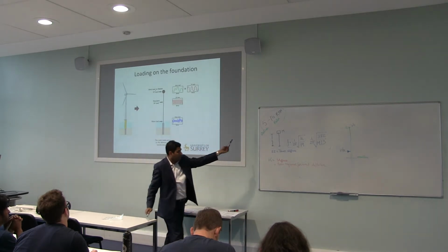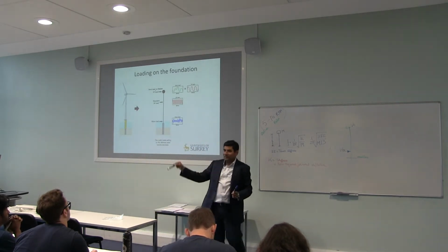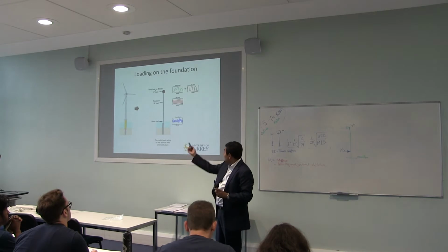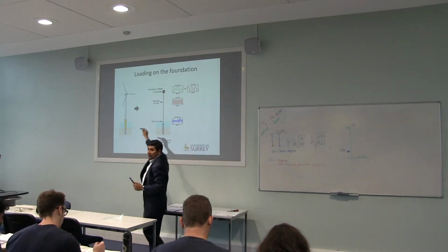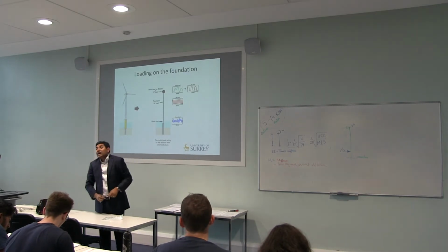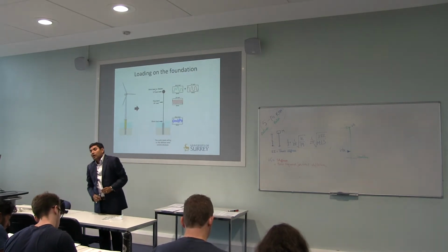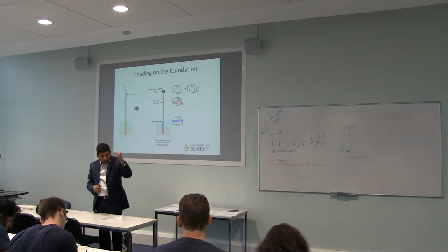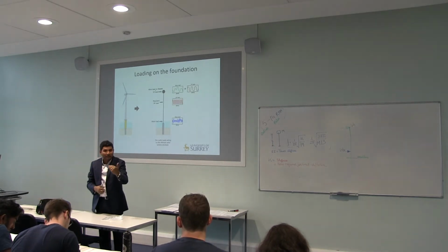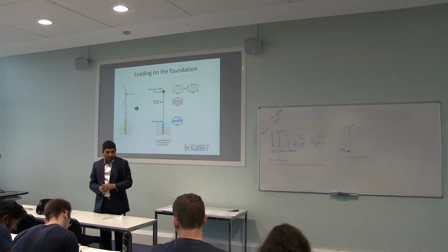If it is moving at 5 RPM, the shadowing will be 5 times 3, because there are 3 blades. So that's 3P, for the blade shadowing effect. How does the blade shadow the tower? You see a drop in the tower load, then again back up, right?